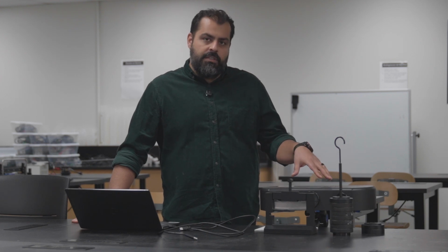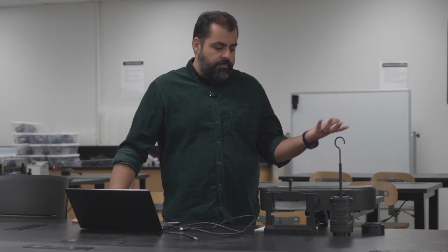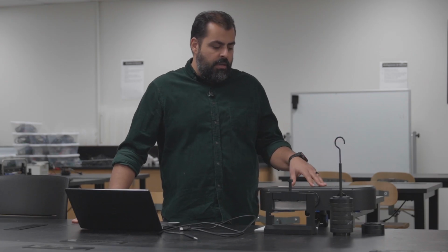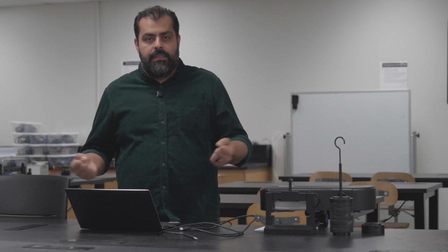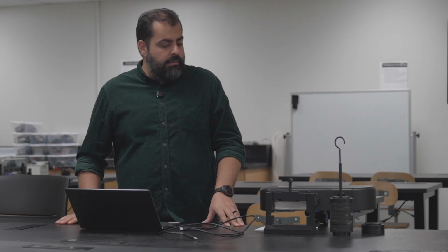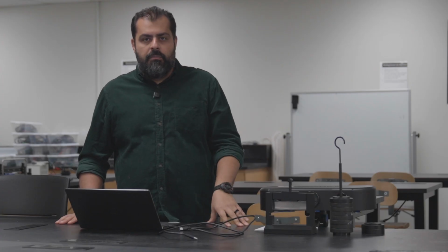This is the educational version of the DIC device, but it works the same as the regular version. Two cameras are going to take some pictures of your sample as you increase the load, or as you do a tensile test, as you do whatever it is that you're doing, and it will compare each image with the previous image and calculate the movement of each point in your sample.